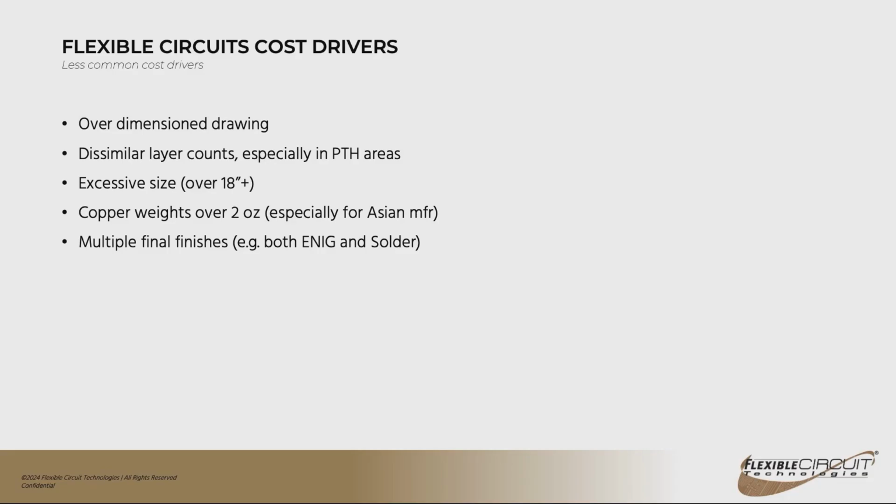Yeah, there's a number of ways you can do that. If you're going to laminate with LCP as your adhesive, it can be done. Keep in mind that it's a thermoplastic. So each time that you hit the melting temperature, it's going to reflow. The temperature is typically over 300 C to do the lamination. It is a very difficult material to work with.